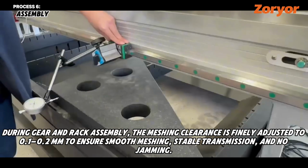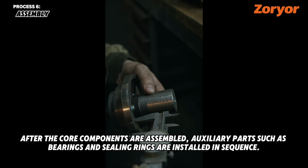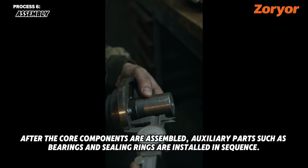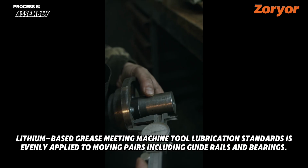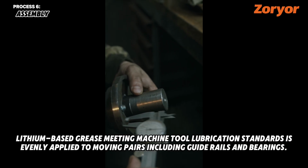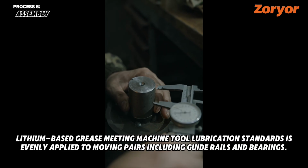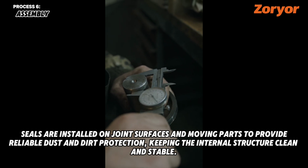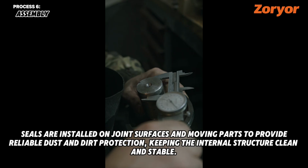After the core components are assembled, auxiliary parts such as bearings and sealing rings are installed in sequence. Lithium-based grease meeting machine tool lubrication standards is evenly applied to moving pairs including guide rails and bearings. Seals are installed on joint surfaces and moving parts to provide reliable dust and dirt protection, keeping the internal structure clean and stable.